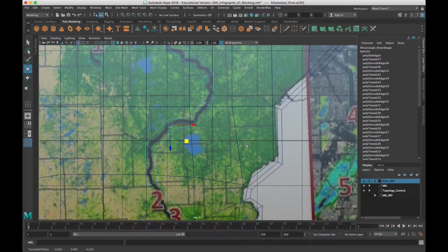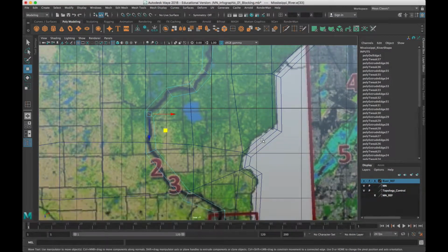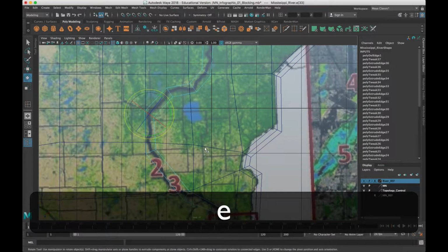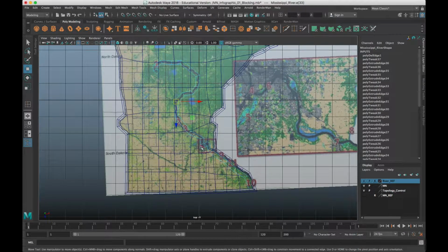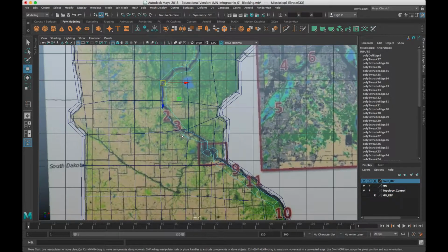Again, it's a common pattern for 3D modeling: you add some geometry and then you go in and clean it up and tweak it and then go on and add more detail. But you want to work at as low detail as possible, as long as possible, because it's a lot easier to adjust this shape when you've got 20 edges versus when you've gone down and subdivided and smoothed it and now you've got 60 edges, right?